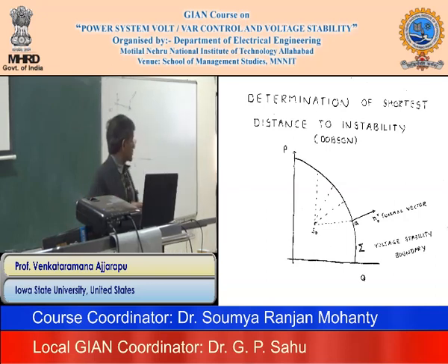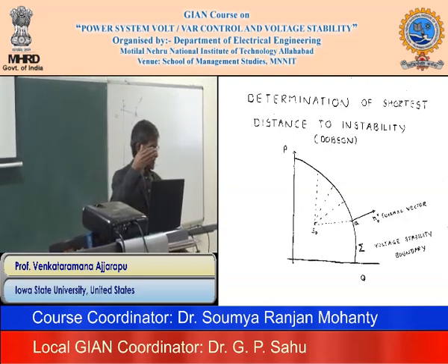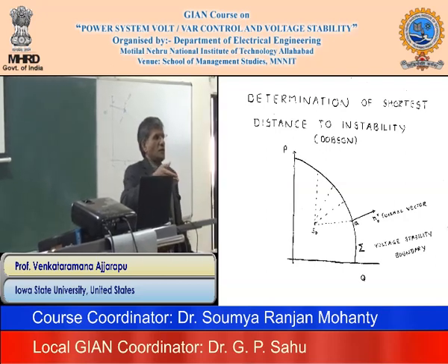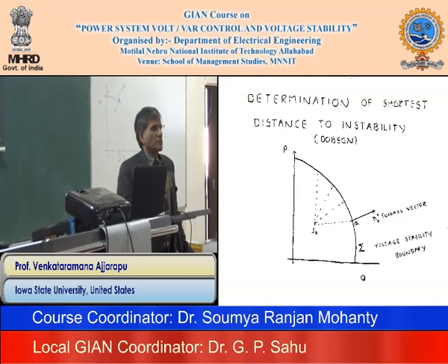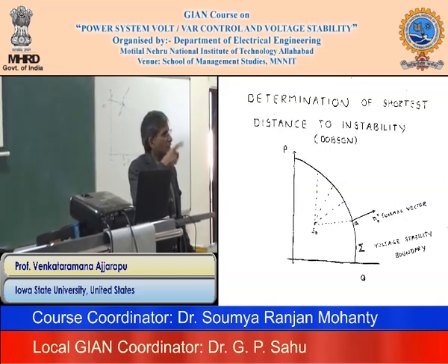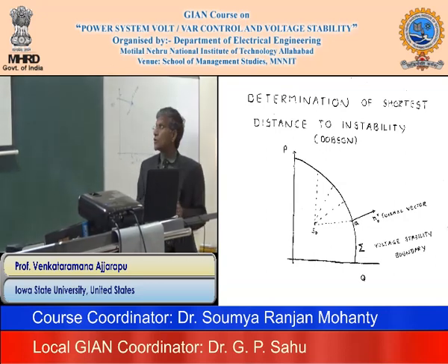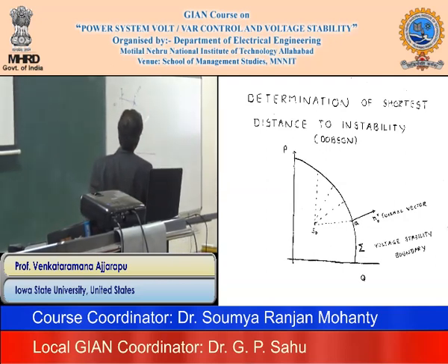Now in the continuation power flow, you get up to the critical point, right? And this is one load direction. When we say PV curve, always this is one path, and I can increase load in different directions. Because of power factor, right? One power factor, you get this one. Another power factor, you get another PV curve, and so on. So now if I know the boundary, the critical boundary that I talked about, so we plotted that boundary.